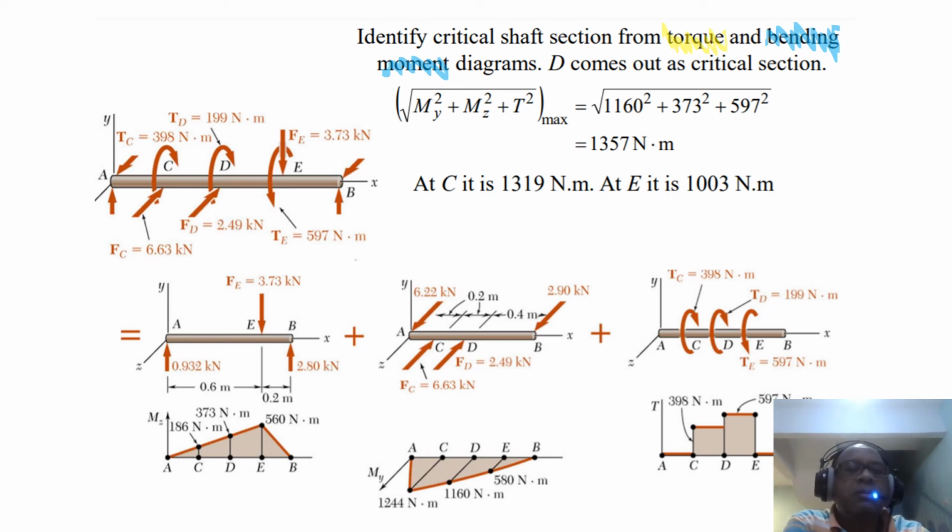So here is for the horizontal, or this is for the vertical one. This is YX. I'm looking at YX here. So we have Y and X. This is the forces from the bearings. So we can do the static equilibrium and find the forces. And this is the bending moment diagram. You can draw the shear force diagram and the bending moment diagram.